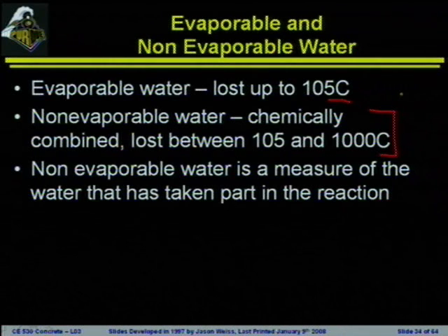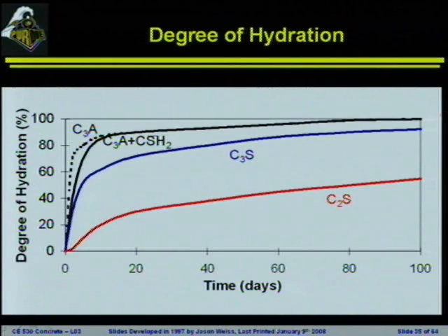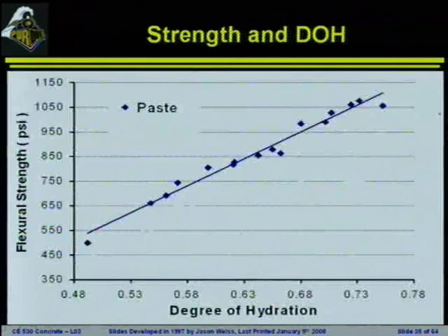And when we start to talk about non-evaporable water, this is typically what we're talking about: a measure to get how much of the water has reacted in the system, how much of the cement has reacted in the overall system.